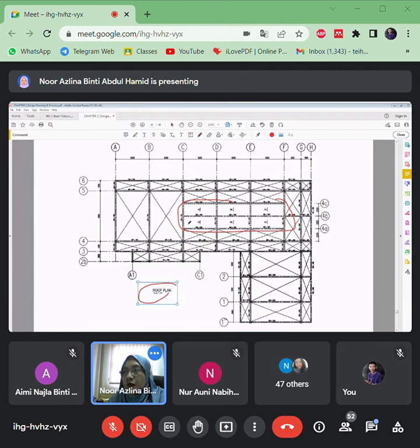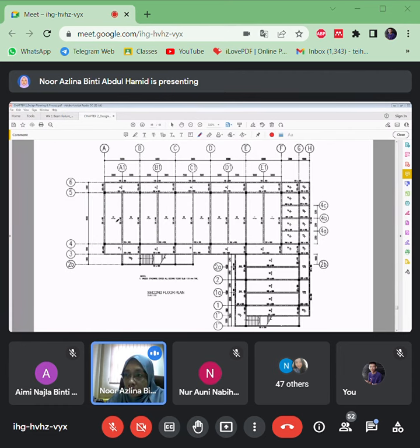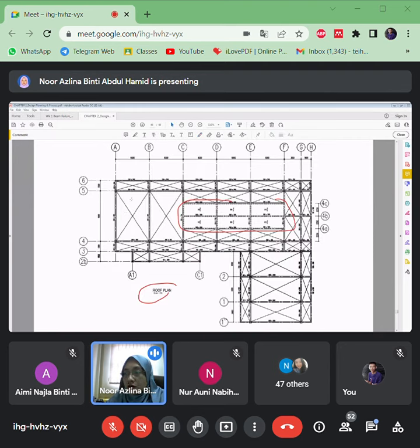So for the space where there's no slab, especially for the roof, we make a crossing. Where there is a slab, we maintain this view. You see, this is a one-way direction, and this is a two-way direction according to the Ly and Lx. So where there's no slab, just make a crossing